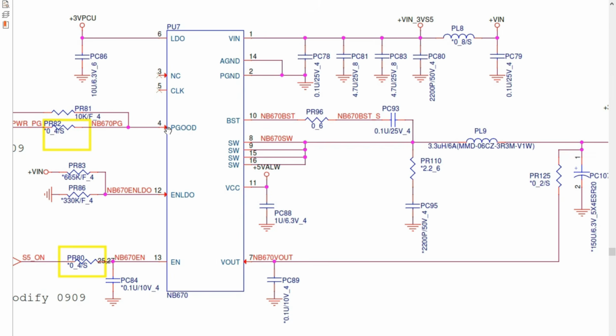And then we have here the power gate. This PGATE means the power gate. So basically this is an enable signal. This signal tells this IC that all powers in the circuit and around the circuit are good, and you can proceed to the next step. If there is a problem in the power grid, the IC cannot continue working. So this is basically the second input. So the VIN, a very important input, and the power good.